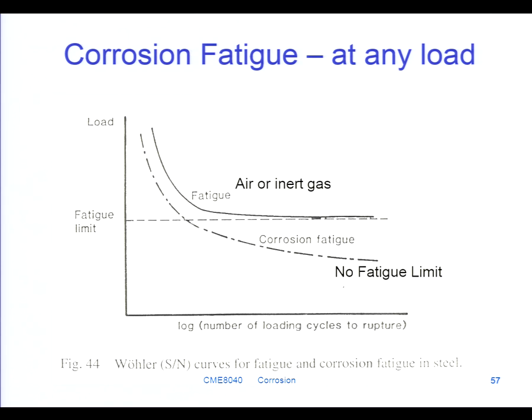That's because wherever there's a tensile residual stress, there'll be an equal and opposite compressive residual stress somewhere else. And that balances the shape. And that stress can be anything up to the yield strength.